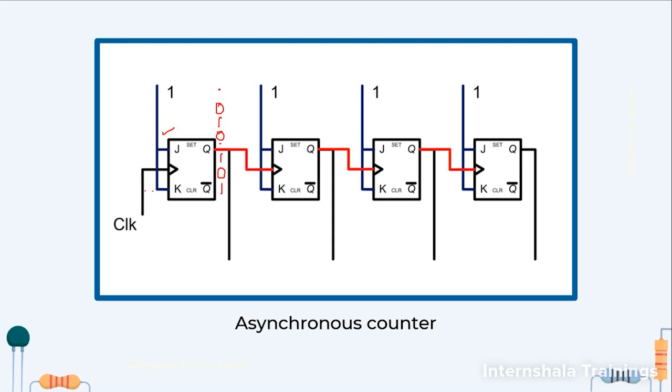This is the LSB of any binary code that we generate. Now one more interesting thing that is happening is that this signal is going as clock to this flip-flop. That means 0 1 0. So whenever this 1 comes, we are getting a rising edge here. So after every 2 clock cycles, we are getting one trigger here as well. So this will also flip 0 1 0 1. Same way this one, same way this one.